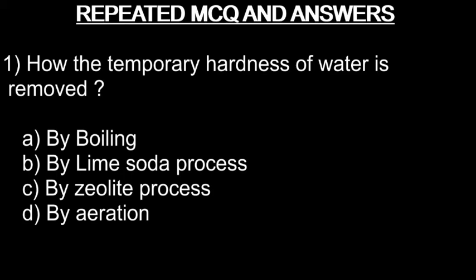Hard waters are undesirable because they may lead to soap consumption, feeling rough while bathing, making food tasteless, causing corrosion, friction losses in pipes, etc. Actually, underground waters are harder than surface water, and hardness of water can be measured by the EDTA method.